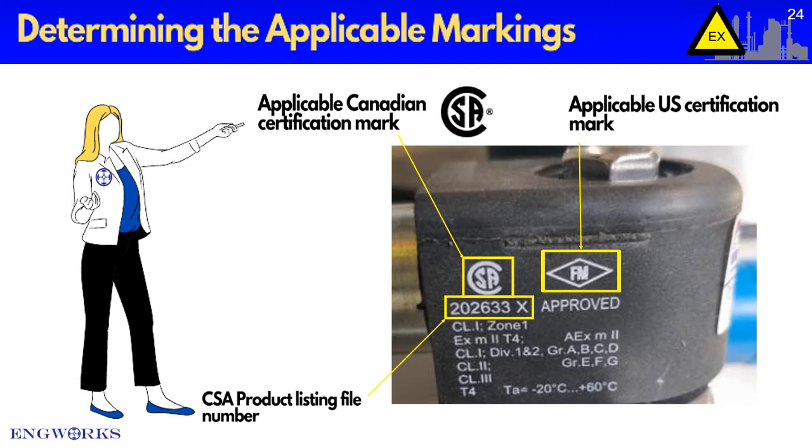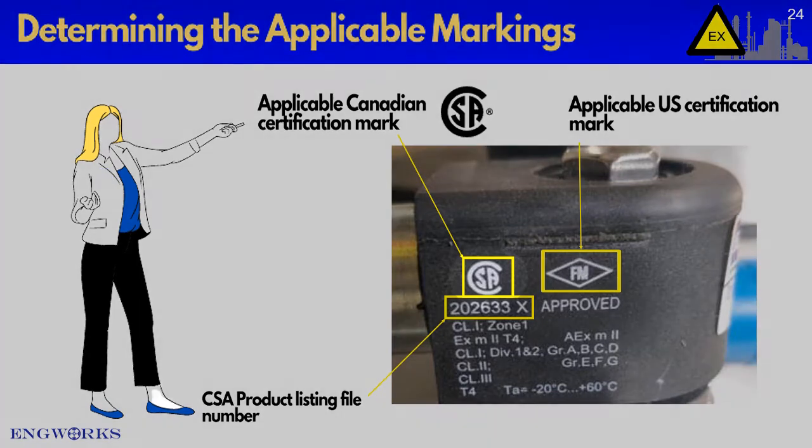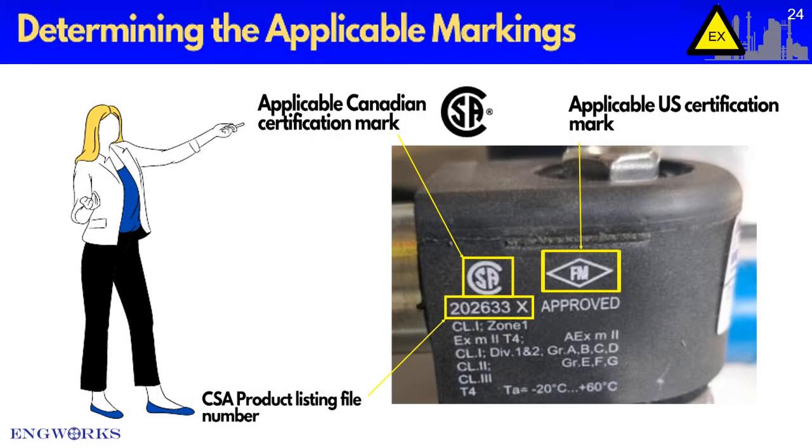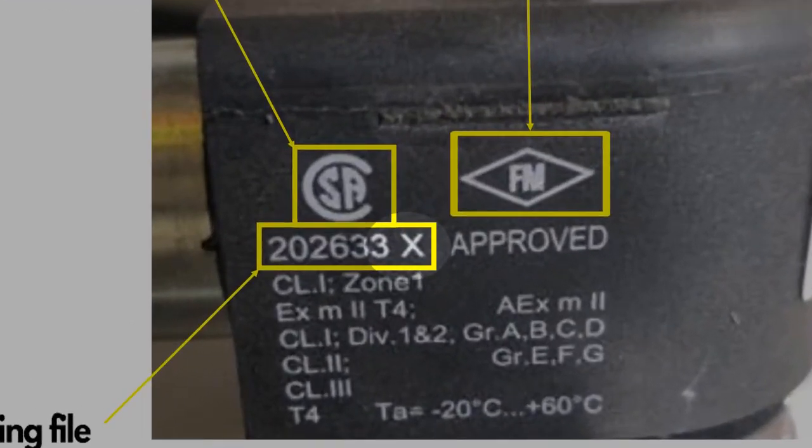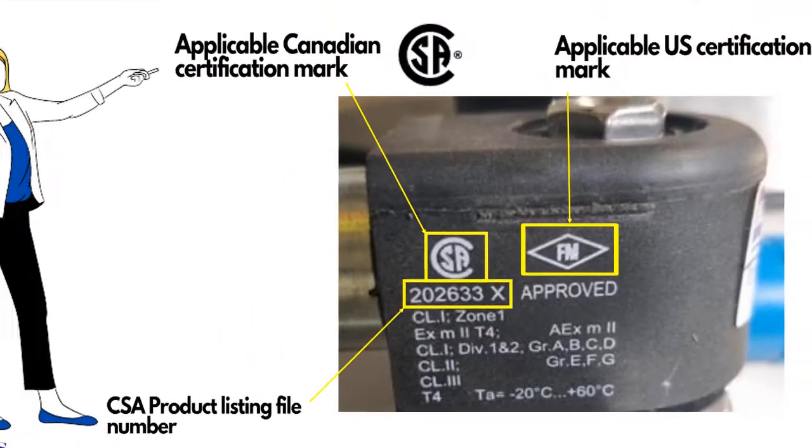As we discussed earlier, the priority is to check for a Canadian certification mark. In this case, the CSA mark indicates Canadian approval. The FM applies to U.S. product standards. Notice the certification number below the CSA mark. This is the CSA certification file for the product. The X beside the product indicates there are special considerations concerning installing this product.